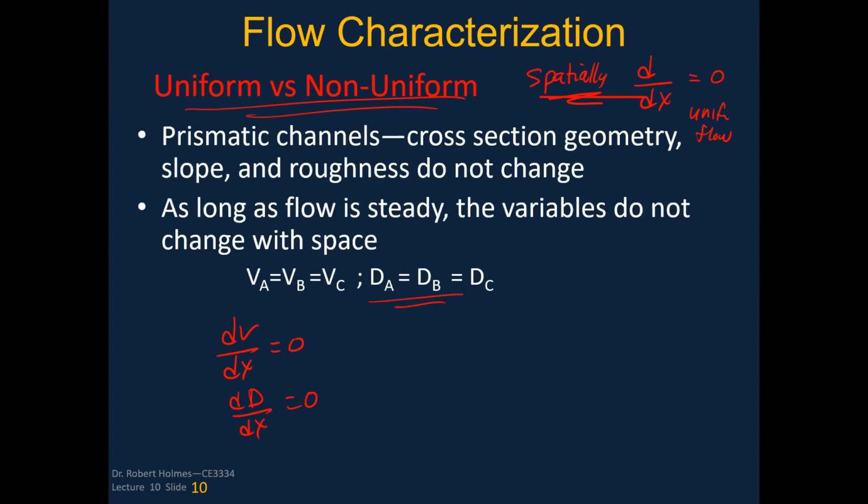One thing I want to note is here we've got depth. This is actual depth of the water. We could also have designated it Y. That's also one common way to refer to depth. Don't confuse this necessarily with hydraulic depth. Just want to call that to your attention, which is area divided by top width. That's not what we're talking about here. This is just regular depth.